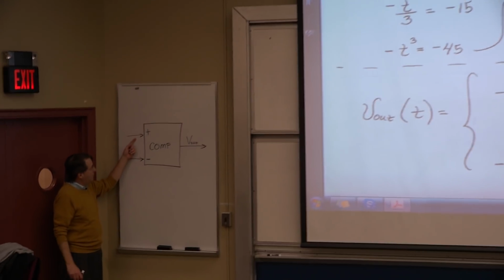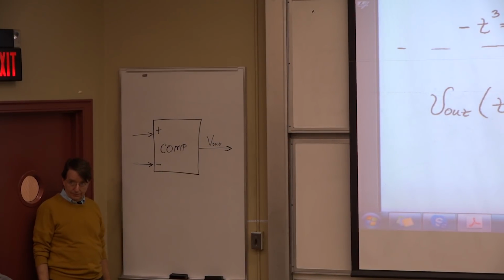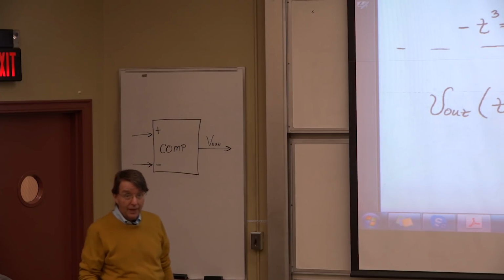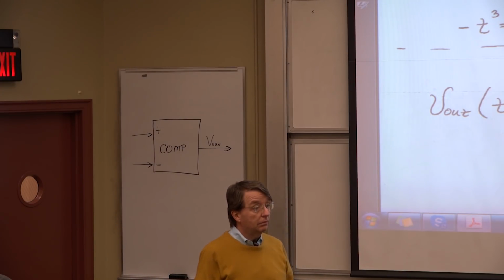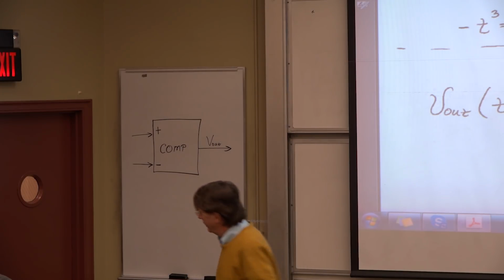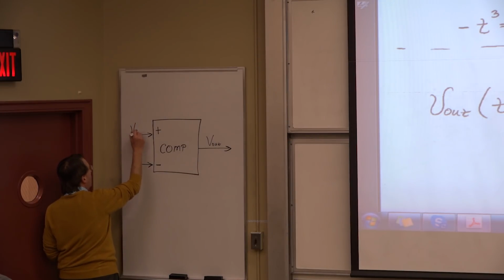If the positive input is a little bigger than the negative input, we get, let's say, positive epsilon. And what's the gain that the op amp is born with? 200,000. So epsilon times 200,000 is 15. So wait a minute. What have I just said? This is V positive. This is V negative.